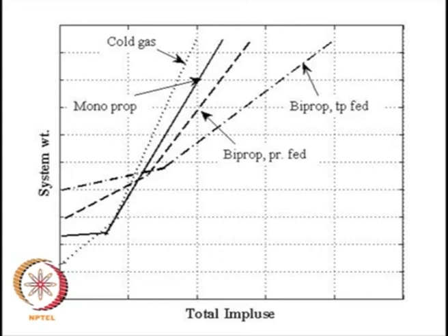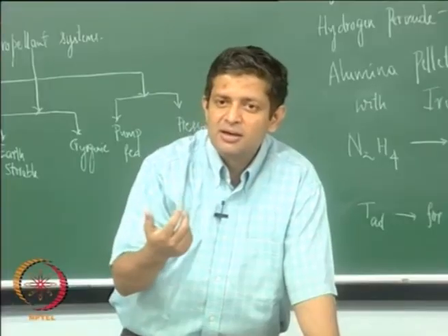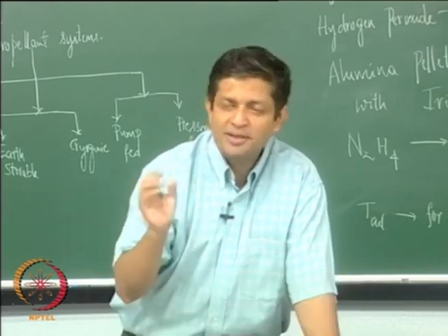So if your thrust is large and as well as burn time is large, then you are going to have a lot of liquid in the tank. So the tank needs to be filled at something like 30 to 40 bar. So the inert gas bottle weight goes up as well as the tank weight goes up, okay, because if you remember from your structures, it is PD by 2T, right. So the thickness goes up as the pressure goes up.